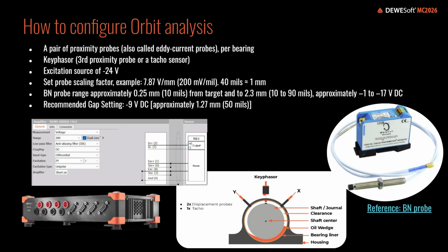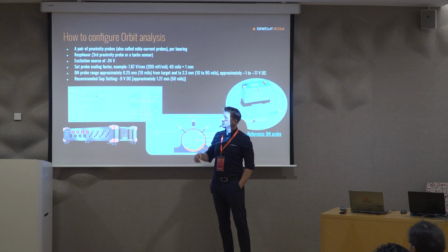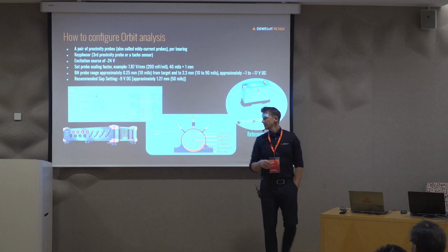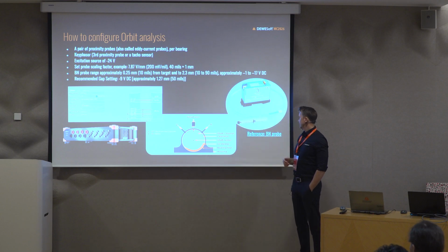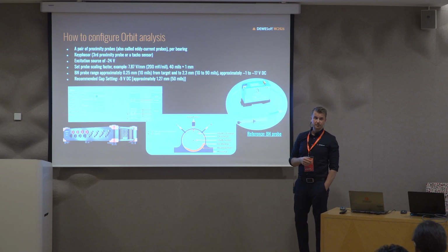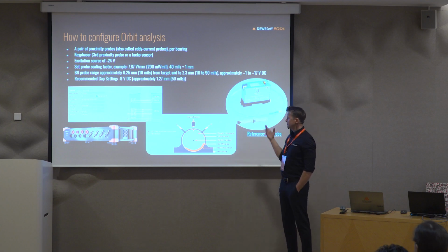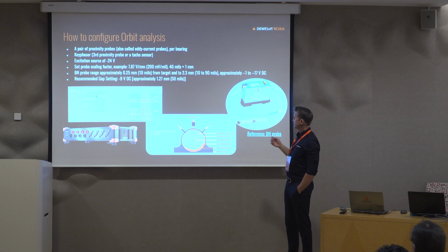Then let's talk a little about how you connect this, because those proximity probes normally need to be conditioned. They need some kind of power. If you want to do that with the Dewesoft device, you can do that with, for example, the LV module, where we can excite the source with up to 24 volts, which probes like a Bentley Nevada probe or Micro-Epsilon probe would like. Some of them don't require this, but many of them do.